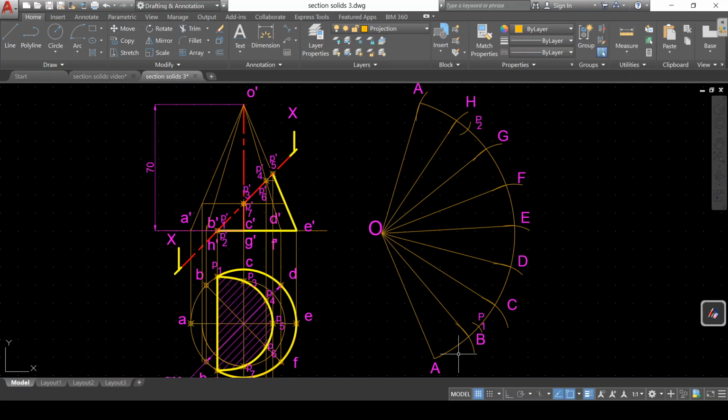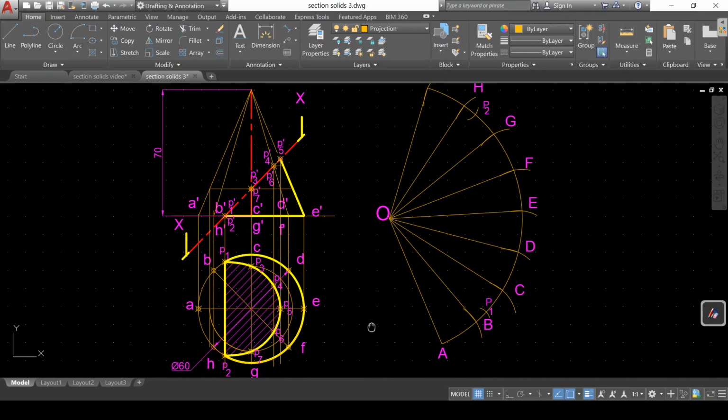OA, we have opened it from OA and got this development because the length of chord is length of arc. That is our assumption. Approximate method we have used here to get these markings on the base. So we have got this. We have used the naming convention, capital alphabets for the development. So this is how we have been doing it. Now if we open it from OA, this portion is already gone, so it is not existing, so there is no point.